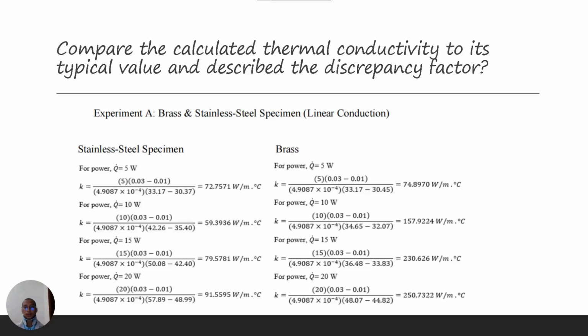All the readings were recorded twice to obtain the average temperature. The average temperature is recorded to reduce this error. The thermal conductivity of a material is inversely proportional to the temperature gradient, according to Fourier's law. In short, the higher the temperature decrease between two connected elements of the same dimension connected to hot and cold reservoirs, the lower the thermal conductivity. When comparing the two materials with increased power input, larger power will undoubtedly generate more heat conducted along the homogeneous and composite bar, contributing to higher thermal conductivity.